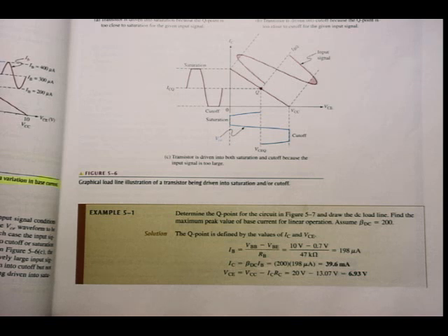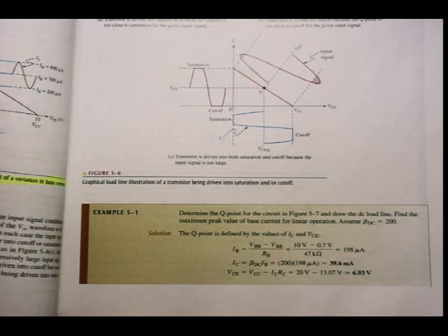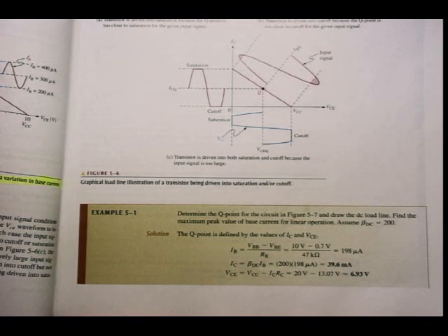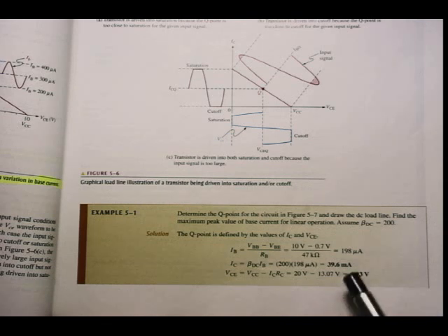Just keep in mind, you have to do your calculations accurately to 3 decimals so that we all get the same answers. Don't round off. You have to work accurately 3 decimals and express your answers in engineering notation. Then I can calculate IC because I know the ratio beta. So IC and IB. So IC is equal to beta DC times IB. I get an answer of 39.6 milliamperes.